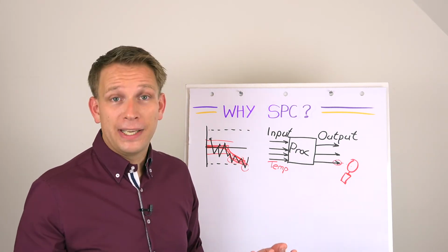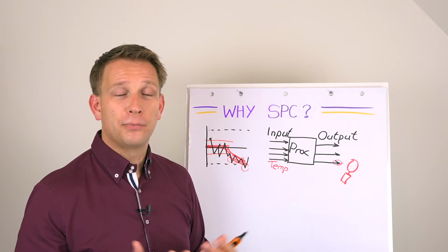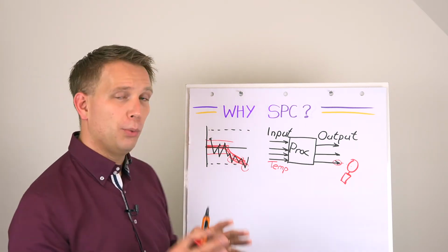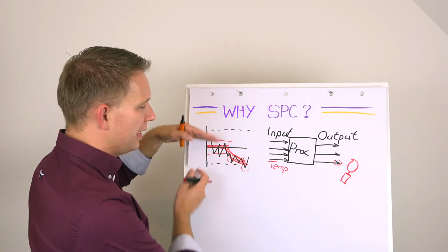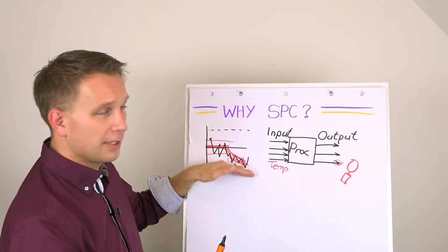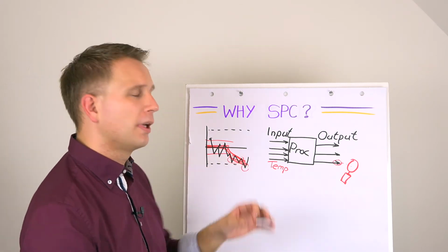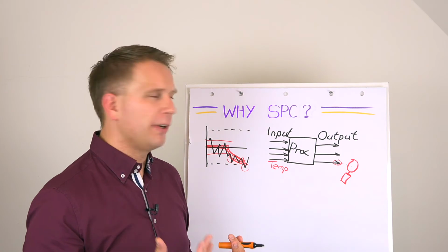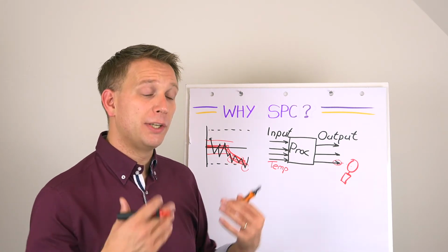And this is a very nice thing to use for predictive maintenance. So you basically follow temperature, you know that when you have a clean machine, it always stays within this. And at some point you see, oh, it's not transferring enough temperature anymore, and you can do something about it. This is not very pure statistical process control because you really know that it will happen.